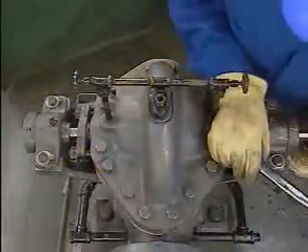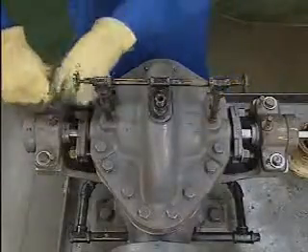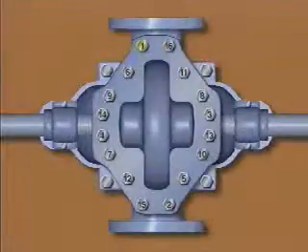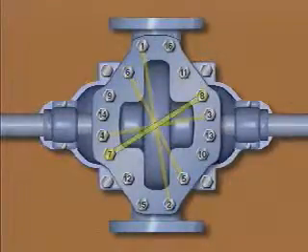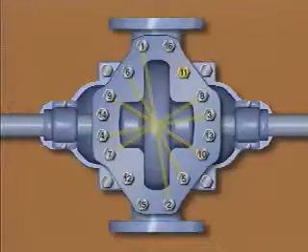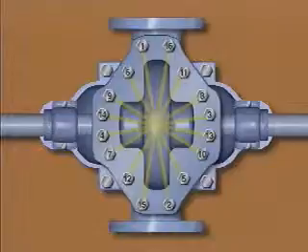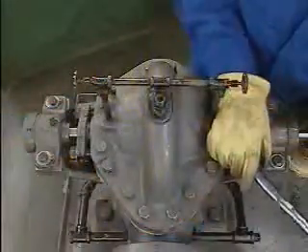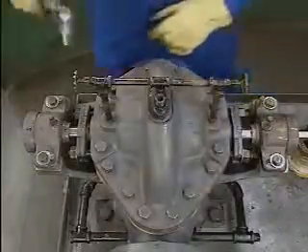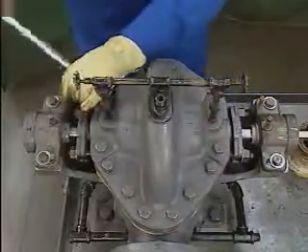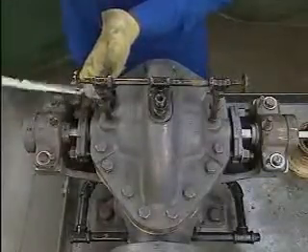The pump's manufacturer recommends that the bolts be tightened in a specific sequence to prevent damage to the sealing surfaces. This is the tightening sequence for this pump. Like other tightening sequences, it is a crossing pattern. The mechanic follows the pattern, crossing back and forth until all the bolts are tightened to the required torque value. He will repeat this pattern several times, gradually increasing the tightening pressure in several stages. If this tightening process is not followed, the sealing surfaces could warp, or the gasket could be improperly compressed.